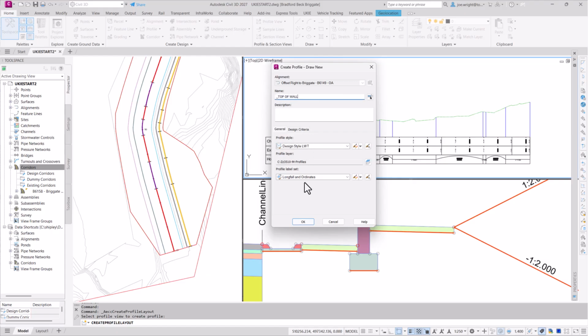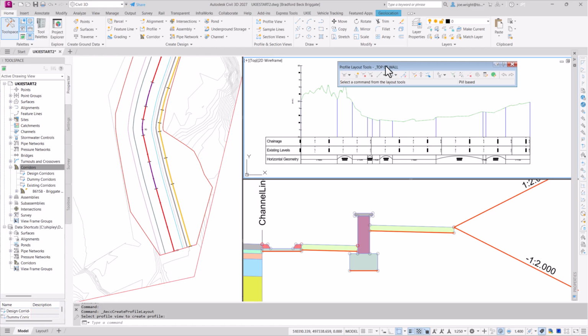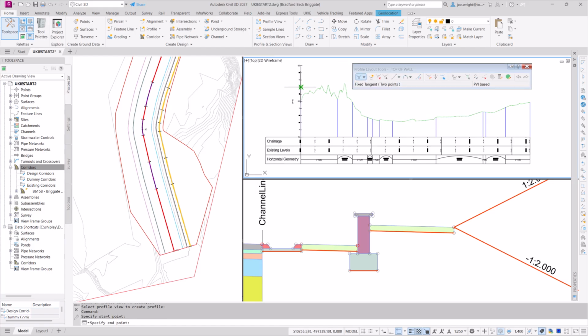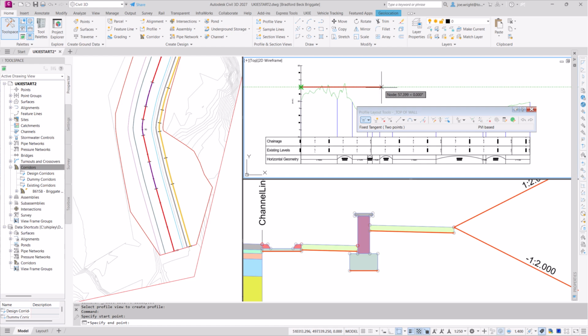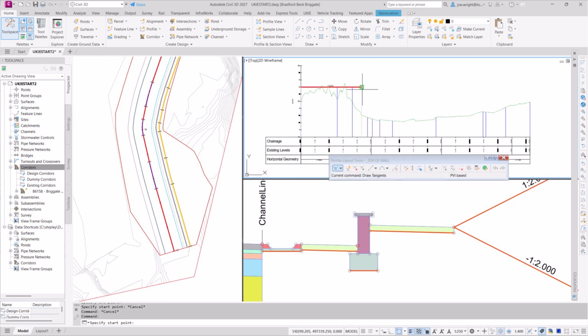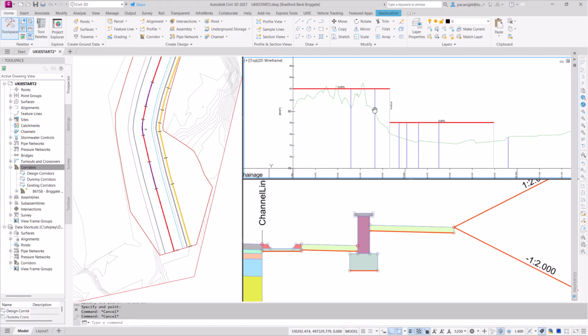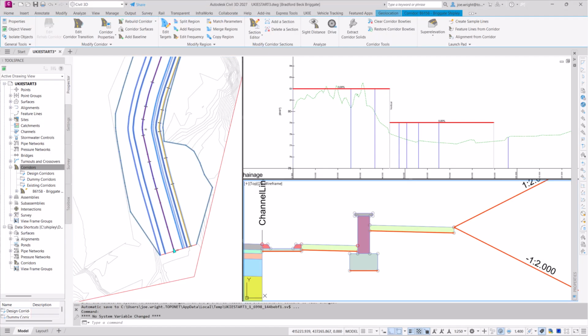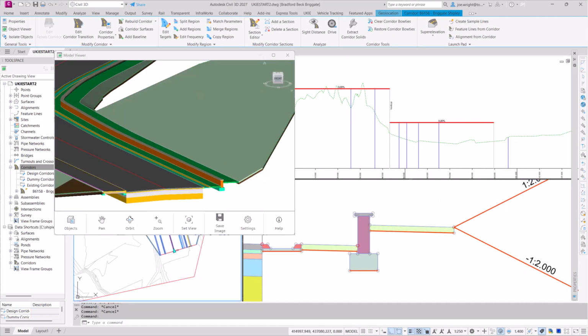And then using the good old Civil 3D profile tools, I'll draw where I want the top of wall to be. I'll have it high here and a bit lower there. Essentially, where there's no profile, it'll just default to the height on the properties sheet. I want to show this change live, so I'll drag back the model viewer.